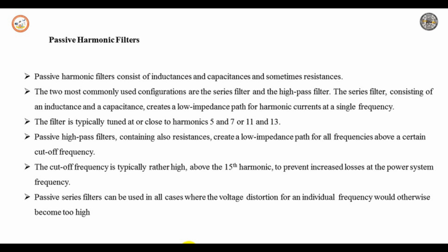Converters based on voltage source converters can also be used to mitigate harmonic distortion as long as the switching frequency is sufficiently high. A whole range of algorithms are being discussed to mitigate the voltage distortion without the need to know the current emission. Such equipment could be installed at a central location in the system. Commercially available equipment is still based on open loop control.